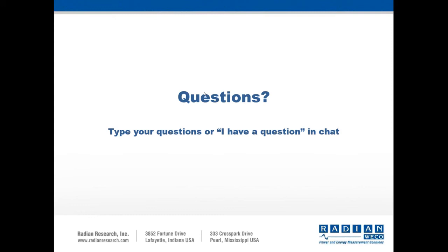In that case, if we want to test on the basis of number of pulses, then what do we set at the test duration? Is it going to be 0 or something else? Or is it going to be the actual time it takes for those pulses to be tested? If you're looking to do pulse-only testing, then you don't have to worry about what the test duration time is set to. So that can be left at whatever setting it was? Correct. When you select to test by pulses, it will solely look at the pulses column for how long it needs to run the test. It will not look at the test duration time unless you set to test by time. All right, thank you.